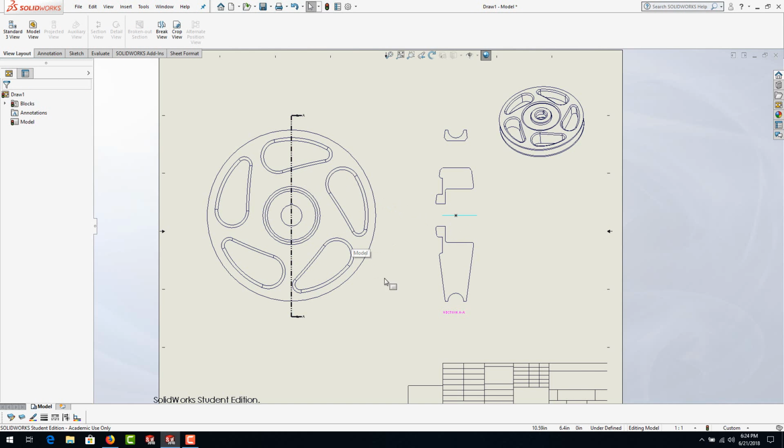When you're deciding what to do with some of this geometry, you can leave it as is, or you can utilize it for the 3D model. If we were to take this profile and copy it into a model or a part file, we could extrude it, but you might notice there's actually a taper on those sides. There's an angle, so that wouldn't do us much good.